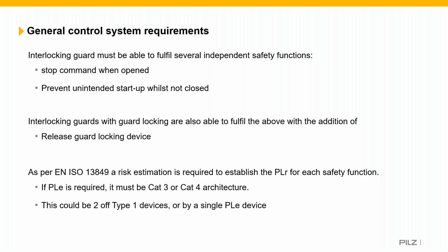So the interlocking guards with guard locking must also be able to, in some way, release the guard lock, but only when we've got to a safe condition to allow that release to happen. And then again, when we open it, we've got to initiate the stop command and prevent an unexpected startup.